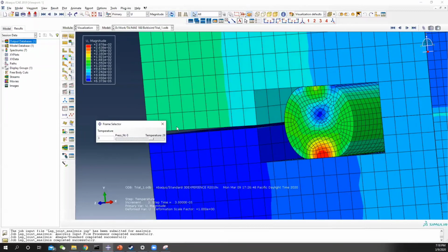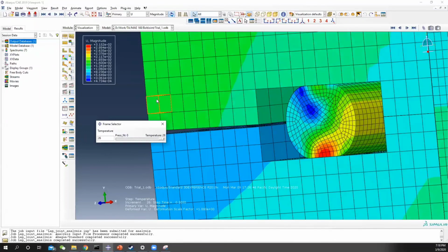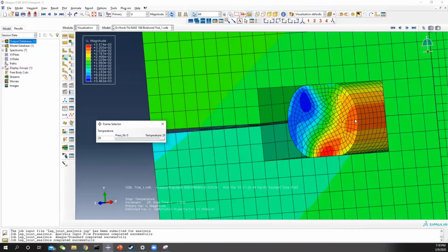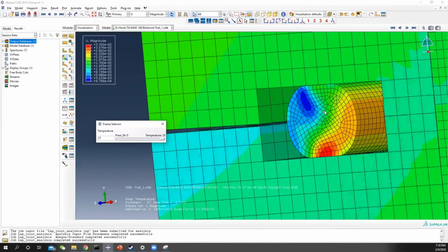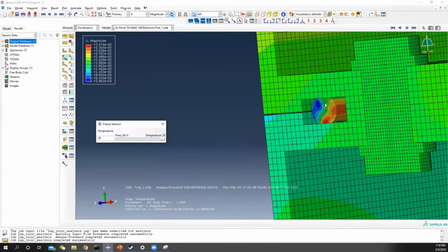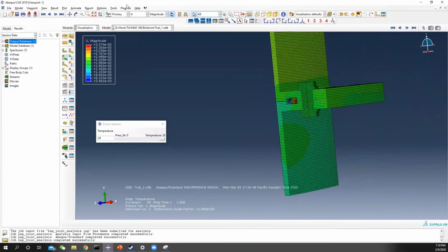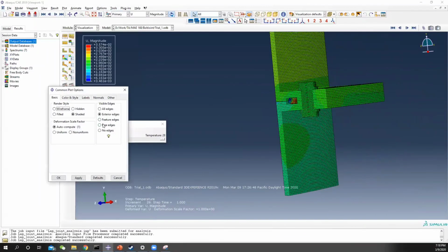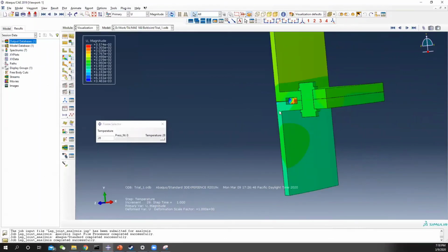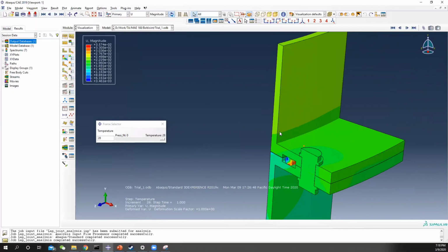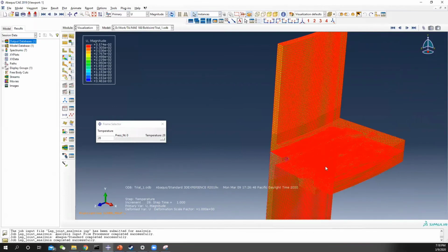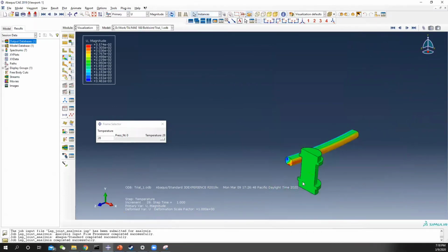Now, if you keep going and apply the thermal load, you can see the thermal expansion of the geometry. See, the geometry is moving to the right and your maximum displacement is applied here. This entire O-ring is also expanded. To see the full structure, first we can get rid of the mesh. And then let's see how the O-ring is doing here. So we select the instance. We hide these two instances, and only see the bolt and the O-ring.